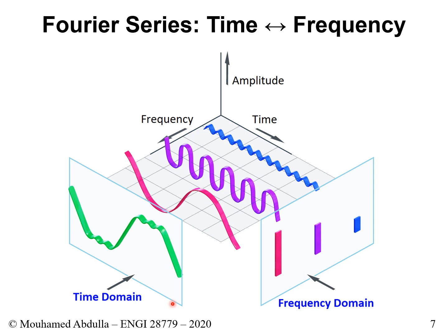Sometimes if you have a signal that is not repeated, let's say a voice signal, let's say somebody's talking, that signal of someone talking is not a repeated pattern. They are saying different words and different sentences as they move along, and therefore the pattern should not be repeated. And in such a case, the signal will be aperiodic. It won't be periodic. If we are working with aperiodic signals in the time domain, then we should always operate with frequency transform.